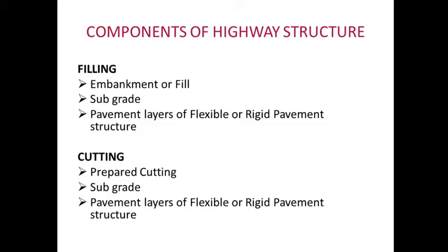The terrains are up and down, forming roads by cutting and filling. Cutting and filling are done to get the desired gradient. Normally, ruling gradient or design gradient is to be provided throughout the length and breadth of the road. Ruling gradient is obtained when the cutting and filling become balanced.